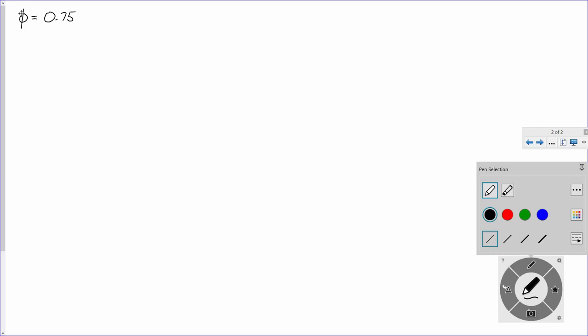Now, we're dealing with a shear problem, so phi is 0.75. Moment is the only situation where you actually have to determine phi. For the others, it's a lookup. Okay? So phi is 0.75.